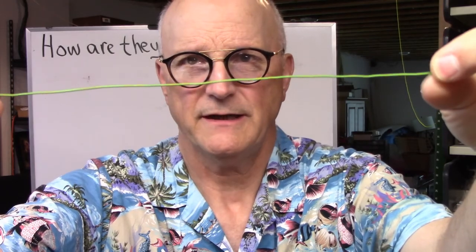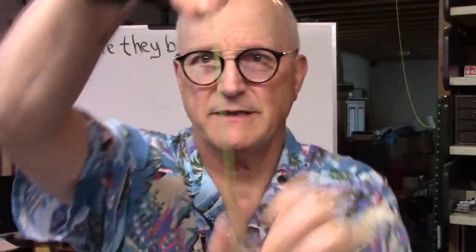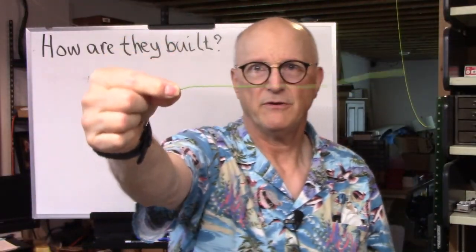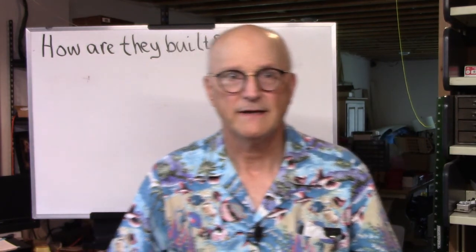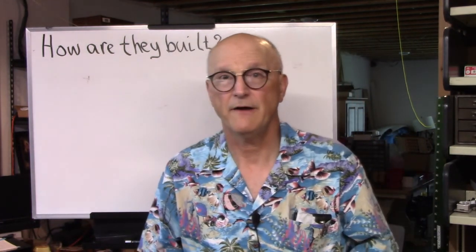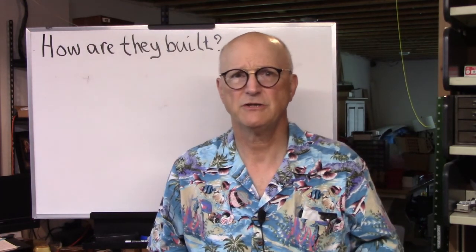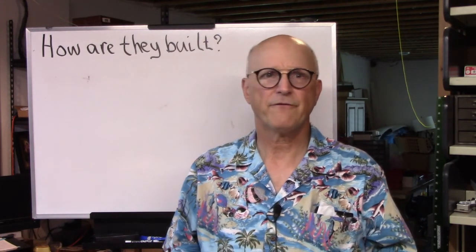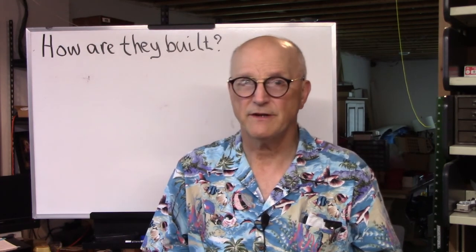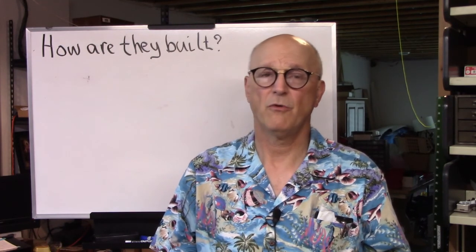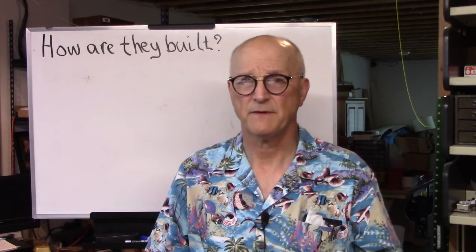This has inductance. It is of itself a simple inductor. As such, when you're talking about RF design or anywhere that you're expecting current to change abruptly, the higher the frequency or the faster the anticipated change, the more critical this becomes.